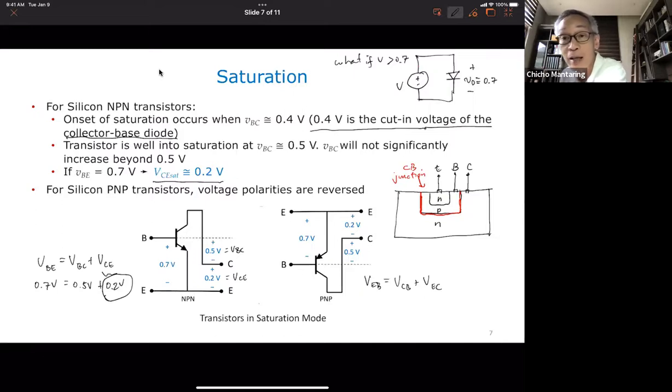But what will happen in reality? In reality, if you try to do this, okay, you are pushing the operating point of the diode very high in its characteristic curve. If you remember the characteristic curve of the diode, this is the characteristic curve. If I try to increase V sub D further, I am pushing my operating point way up here.